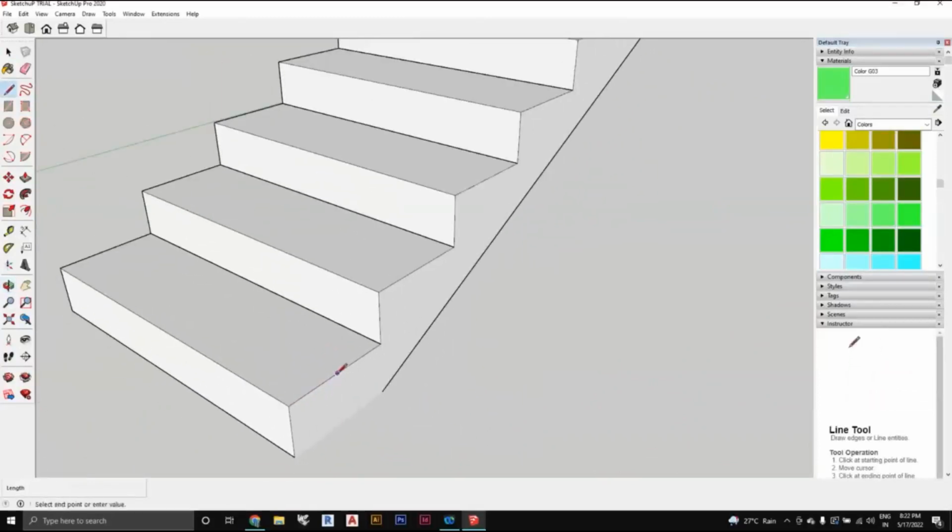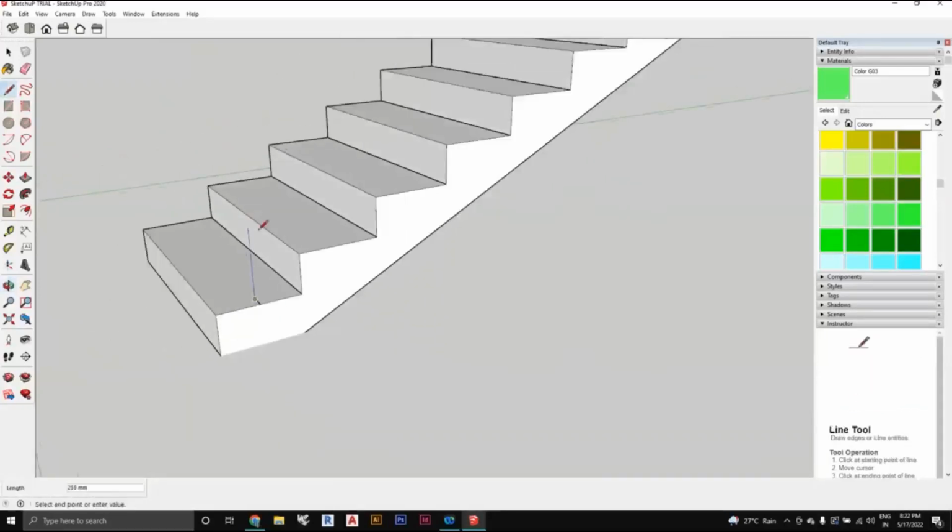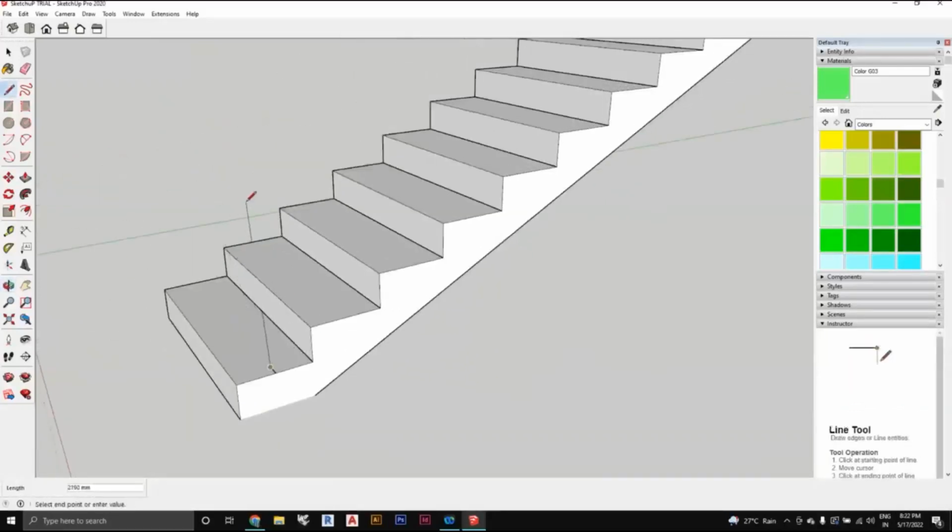From the midpoint I'm making a 50 mm offset, and then I'm going to make a path going 1000 mm up, that is, I'm making a balustrade for the railing. Fine, this 1000 mm, and I'm pressing enter,